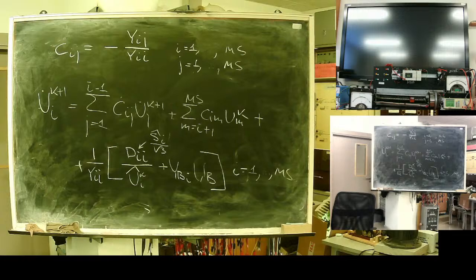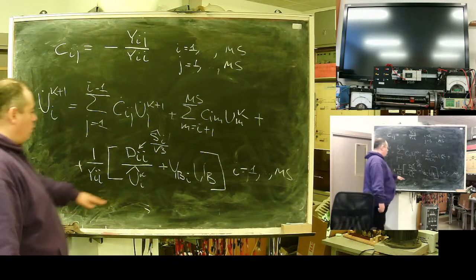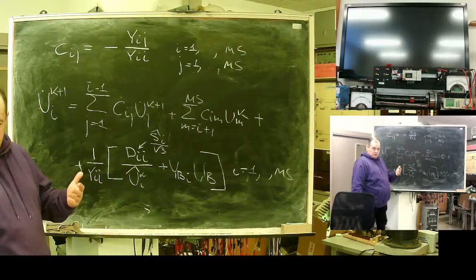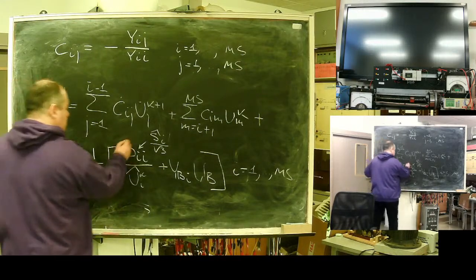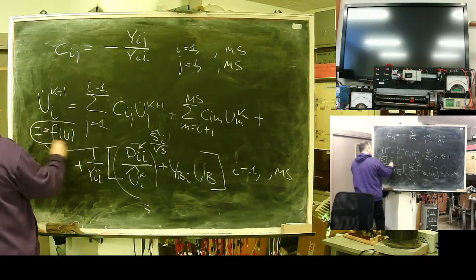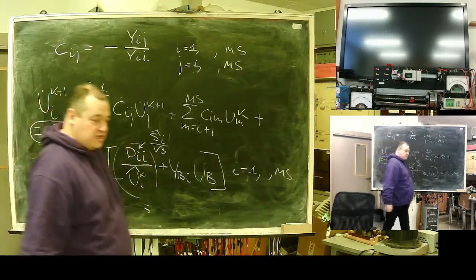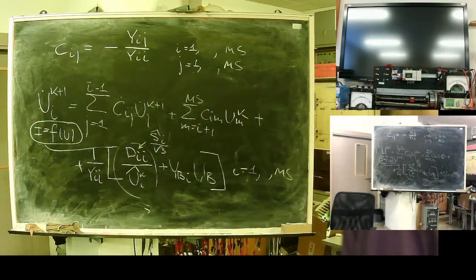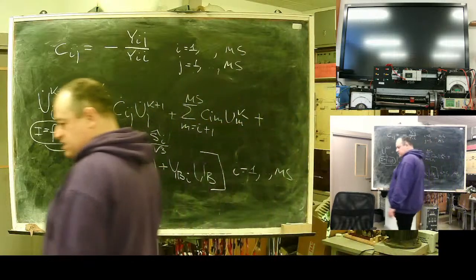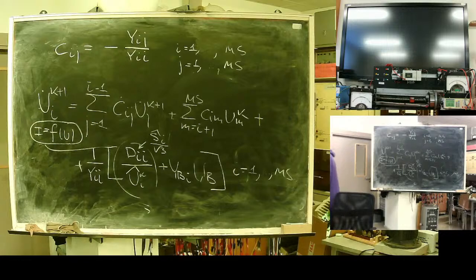On each step, currents representing loads and generations are calculated using the previous voltage. In case you have a more complex law of control, substitute this with the current being a function of voltage. You can put any control law here and it will work. It's a way to solve this nonlinear problem.